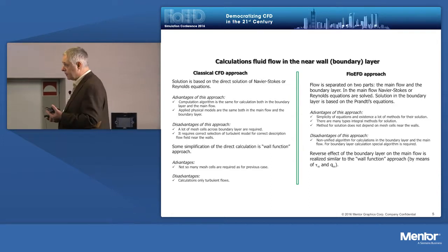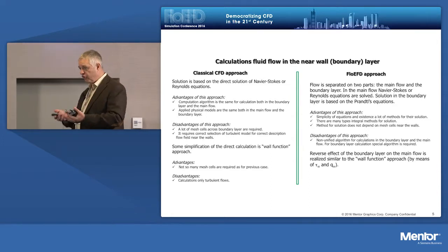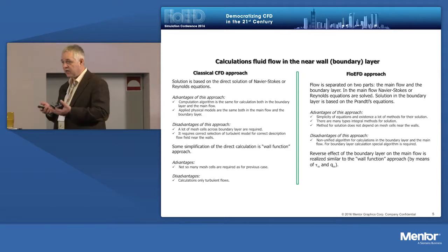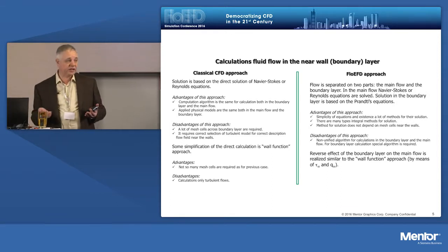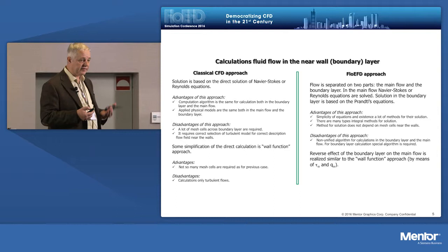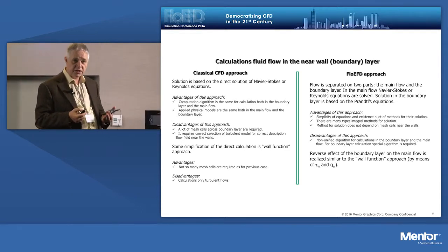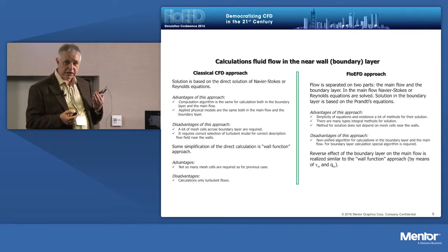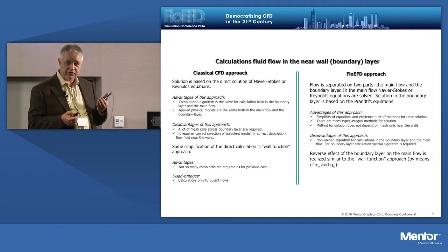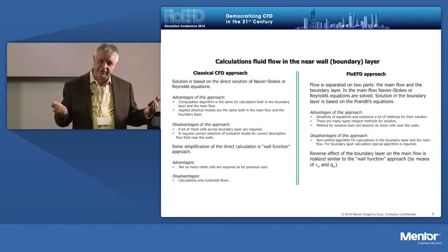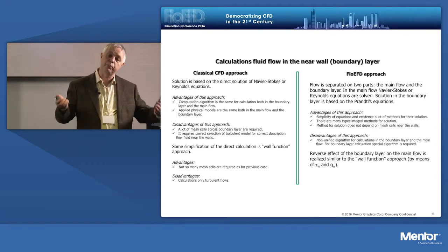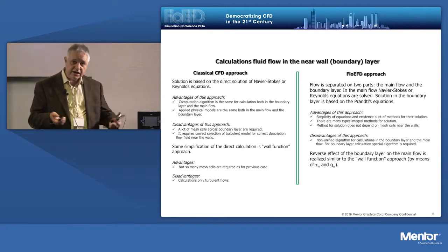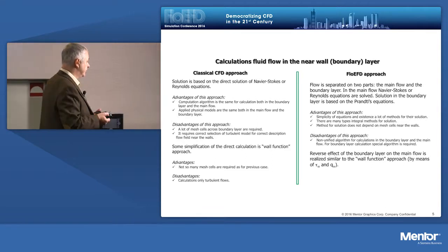What is the main idea? We calculate the flow field by one algorithm and the boundary layer by another one. So the advantage is easy: we are saving computational resources. We do not need a lot of turbulence models in the boundary layer, because we can take the best from all of this variety of turbulence models and put it via analytical methods inside our boundary layer theory.